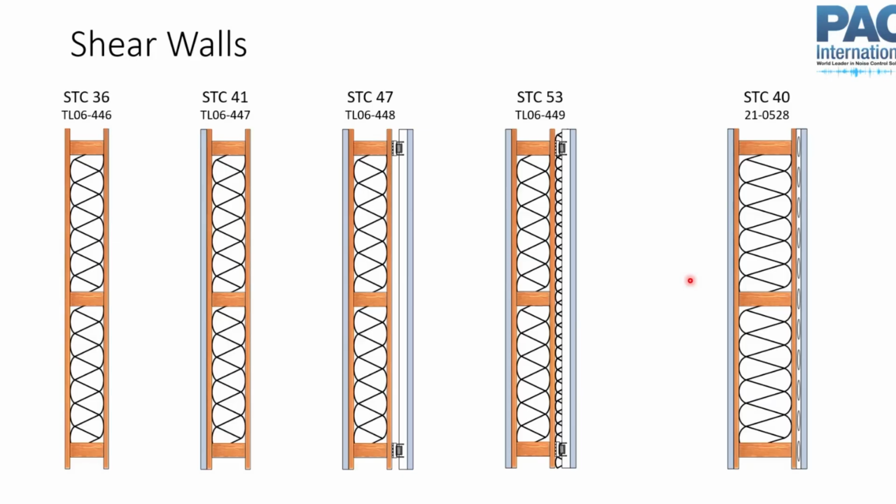So you say, okay, well, let's put the isolation on the corridor side. Well, but then you put the shear panel on the kitchen side. Well, but if you put the shear panel on that kitchen side, that goes up when the building's framed. And then your contractors, your subs for electrical and plumbing have to come through and run all of that in the wall and then go through that shear panel to get to your kitchen. That adds complication and some cost to it. So often you wind up wanting to put the shear panel on the corridor side too. So then you wind up with shear panel and acoustic isolation on the same side, even though you only have a single shear panel. So that can become an issue. So you've got to look at those kinds of details.